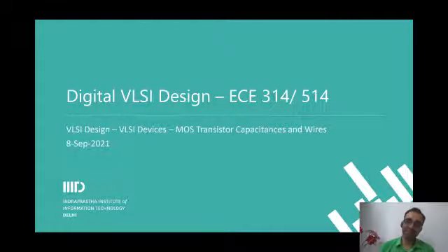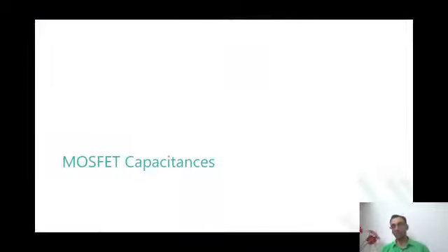So let's move to today's class now. We've looked at MOS capacitances, and we've looked at MOSFET also as a capacitance, where we said that the high frequency behavior and low frequency behavior of a MOSFET capacitance would be the same. You remember this? We talked about this not just in the last class, but also in the office hours at much length and in much detail. So why is that the case? Because there is a source and drain region, which is a cache of charges right next there. So if you need more electrons or holes, whatever you need, you will get them from that region.